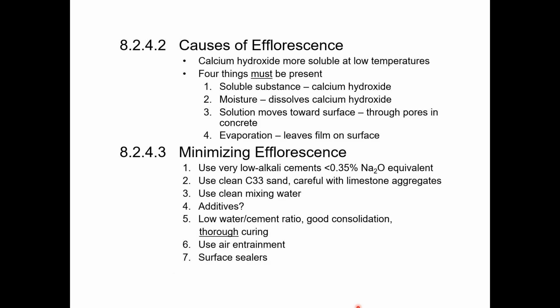But if, let's say, the differential camber was 1.5 inches, and you're supposed to be putting a 2 inch topping slab on it, well, 2 inches from where, right? Are you measuring 2 inches from the double T that's got the higher camber? If you are, then you end up with a much thicker topping slab than you're supposed to have. If not, then you end up with a much thinner topping slab, at least across that double T. So it can create issues.